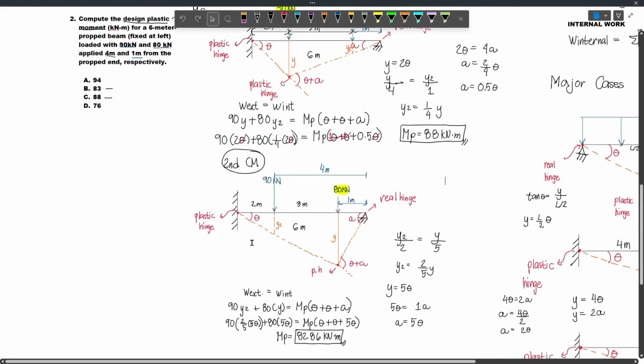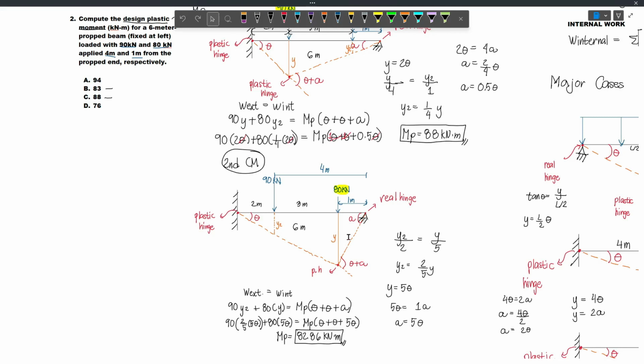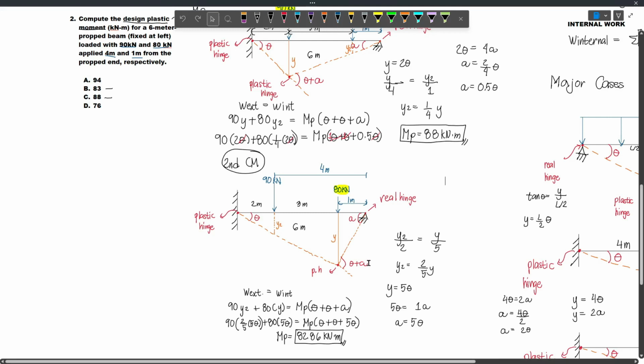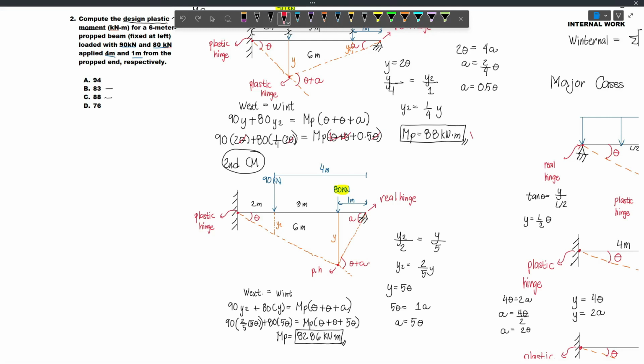Now again, this is different from the first one, where we chose the smaller load, because our question was what is the maximum load, that is, what the beam can carry before it collapses. But here, the essential question is what capacity, or how much FyZx, is needed so that the beam can withstand the applied loads. So our choice is the required moment capacity.